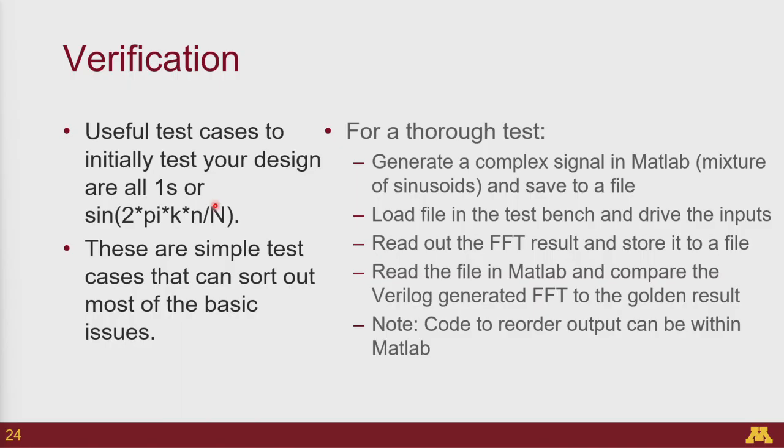And in that MATLAB script, you would convert that to a hexadecimal value, which you then pass as an input to your test bench. All your test bench would do, as you've seen in code before, is read a file line by line and pass that input into the design one input at a time.